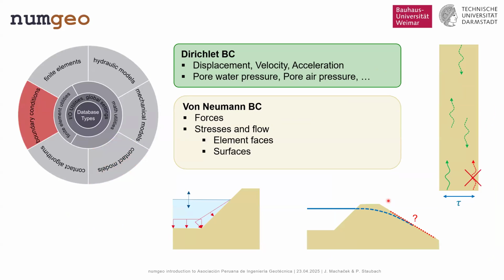Now, obviously, every finite element code needs also boundary conditions. So you can apply directly boundary conditions, meaning displacements, velocity, accelerations, pore pressure, pore air pressure. They can be constant or time varying. They can even vary in time and space. On top of that, you can also apply external forces and stresses.